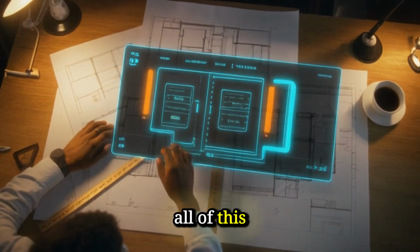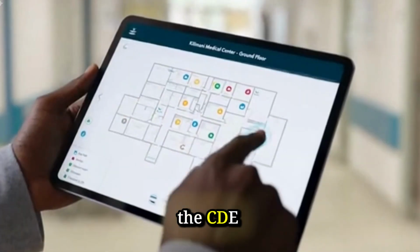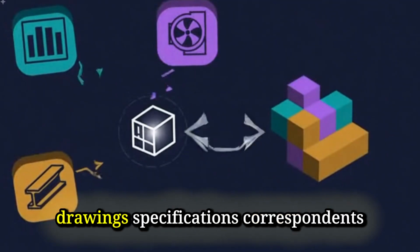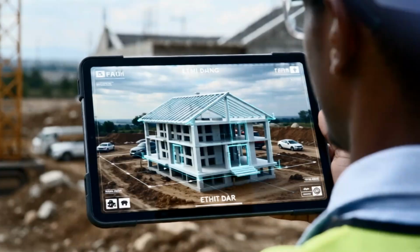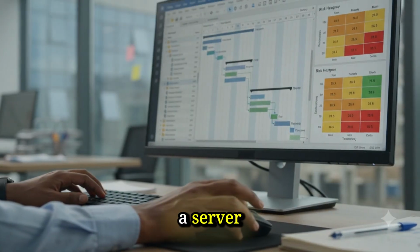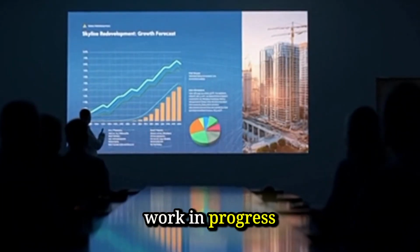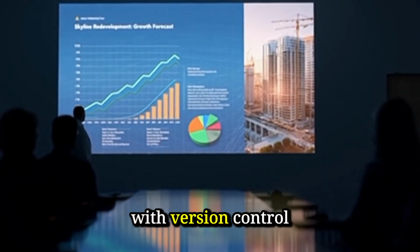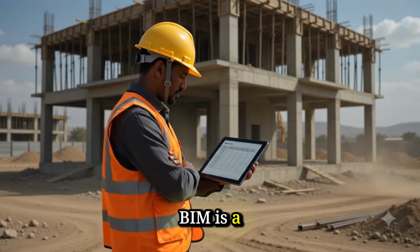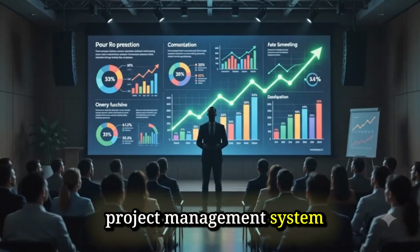Now, what holds all of this together? The common data environment, the CDE. The CDE is the single source of truth where all project information, models, drawings, specifications, correspondence, site records is stored, managed, and shared. It is not a folder on a server. It is a managed workflow. Documents move through defined states: work in progress, shared, published, archived, with version control and audit trails at every step. Without a CDE, BIM is a three-dimensional drawing tool. With a CDE, it is a project management system.